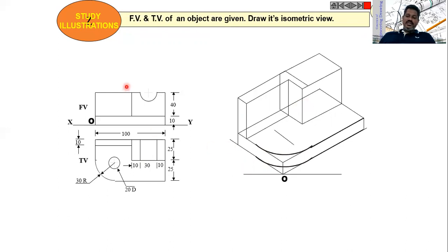And the next is that we need to construct this cylindrical shape, right? And exactly locate the cylindrical portion. And also we need to draw the circle like this. This is a hole with radius 30, and this will be the diameter 20, radius 10. But here also we need to construct the depression, that is the diameter is 30, as you can see here.